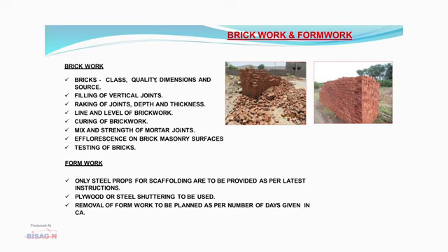Adequate arrangements have to be made for filling in the vertical joints. Raking of the joints, their depth and thickness has to be ensured. The line and level of the brickwork should be uniform. Adequate curing needs to be carried out for the brickwork.